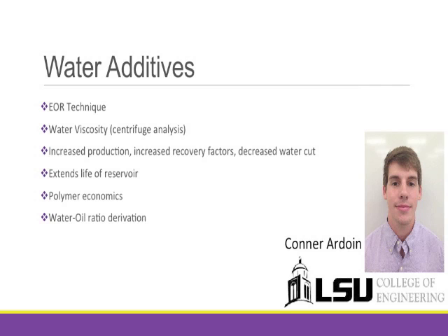One problem experienced in water flooding is that the low viscosity of water has trouble diverting medium to light oil through tight pore spaces because water will flow in the path of least resistance and typically bypass large quantities of oil. Viscosifying the flood water with polymers solves this problem and also reduces detrimental fingering effects. I plan on using a rotational viscometer to measure the viscosity of brine solution versus the brine solution with polymer additives, as well as the optimum polymer concentration.